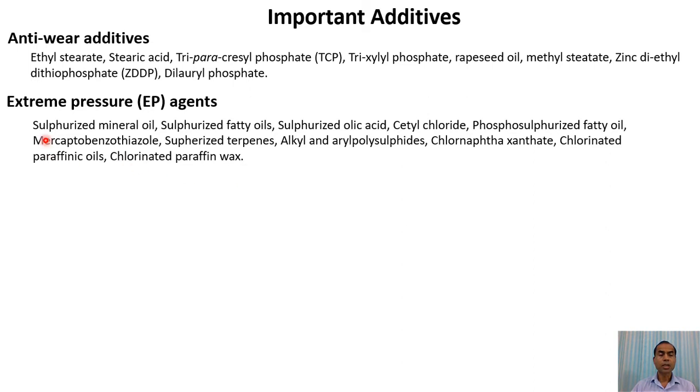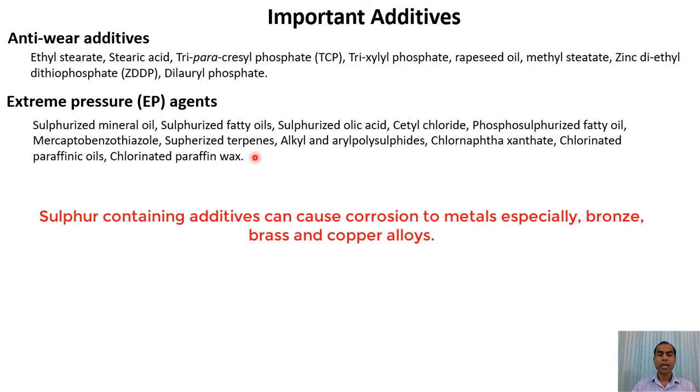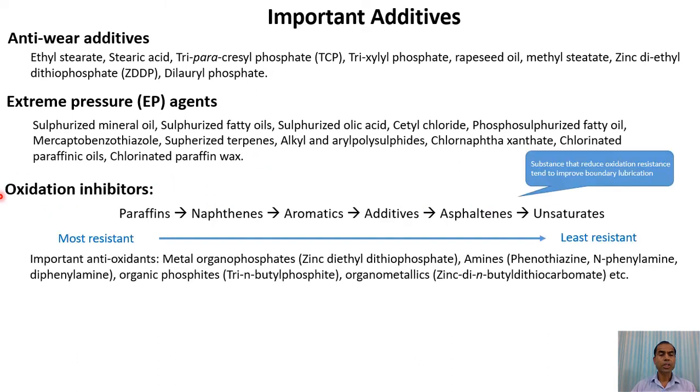There is one issue with extreme pressure agents. These are all sulfurized or phosphorus containing molecules, and they are very corrosive to some metals. For example, they are corrosive to copper or any kind of non-ferrous materials.